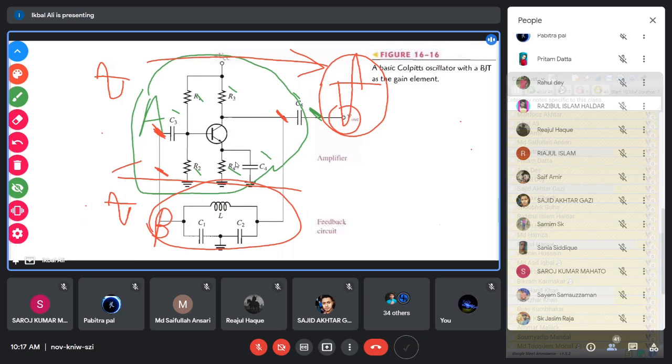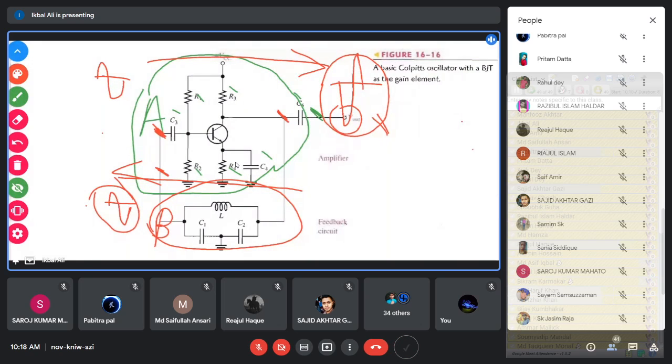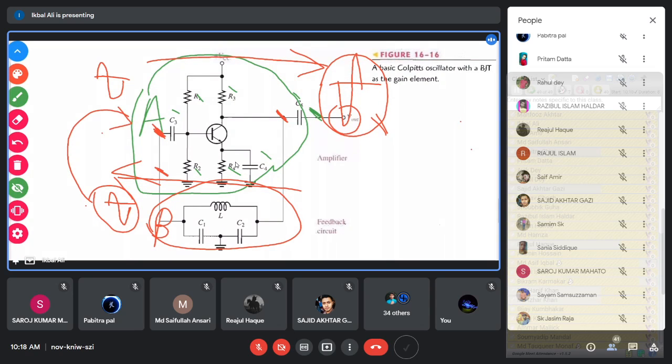again a 180-degree phase shift will be there. And that 180-degree phase shift reverses this signal again to this one. So you are getting a 360-degree phase shift like this. And you see that this signal is again the input of the amplifier. So the feedback signal is again the input of the amplifier. In this way, the 360-degree phase shift of the positive feedback condition is satisfied in this amplifier circuit.